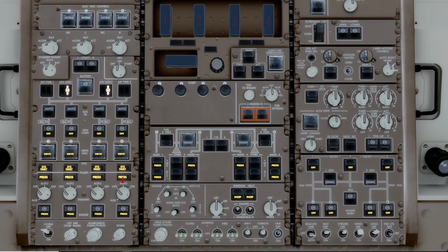System fault lights are illuminated, demand pump pressure lights illuminated, demand pumps are all off, engine driven pumps are on, the pressure lights are illuminated. Again, you can notice from generator control down there's all lights. From the bus ties up there's no lights except for what you have on for external or APU. And that's a good general check to see that all the lights are proper.